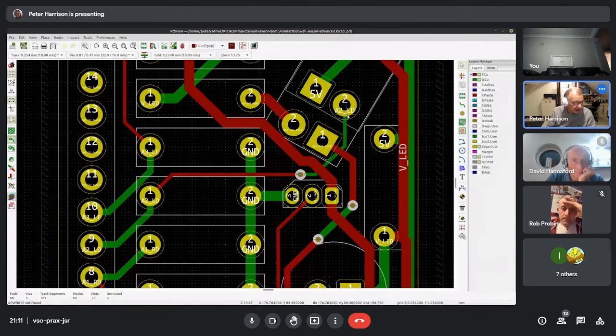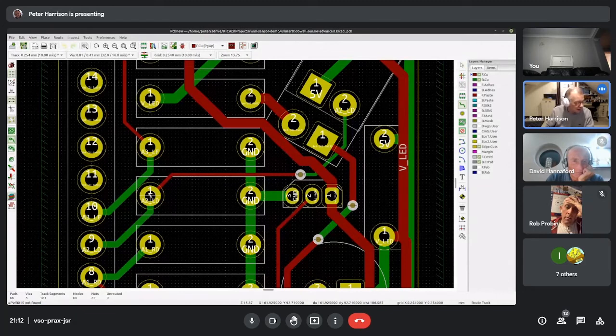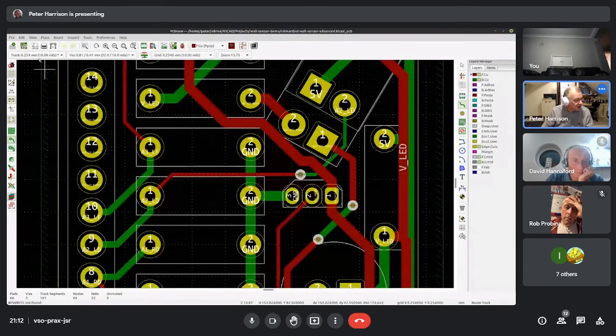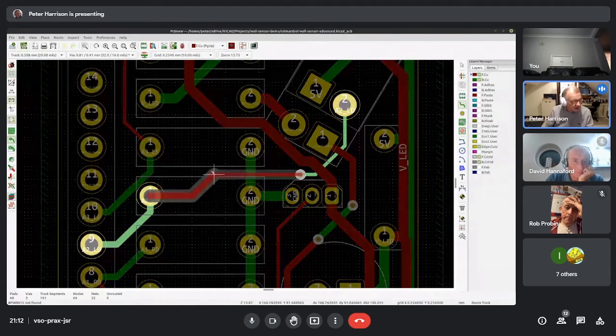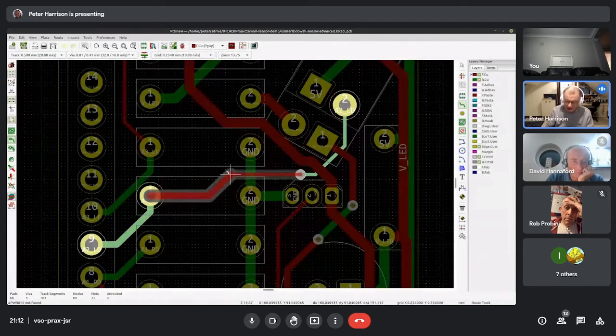No, it's not. It's the photo detector underneath, I think. We'll see in a minute. There's a trace which is much thinner than the others, and I think I would just be happier with a thicker trace. So let's do that. We're on the top copper layer. We'll select the trace tool, and what I didn't do, of course, was change the size. Come up here and select 0.5 millimeter. And I'm just going to come up and fix that. And you will notice that it gets rid of the old trace for me.